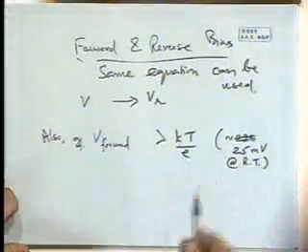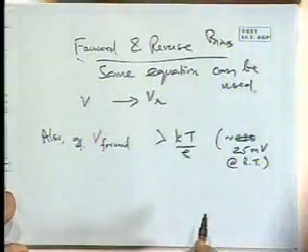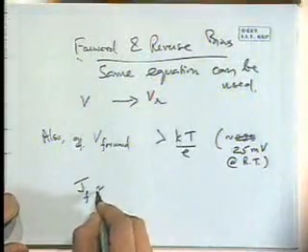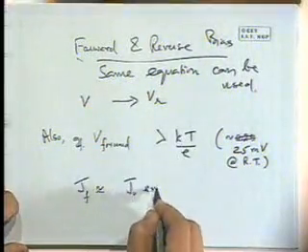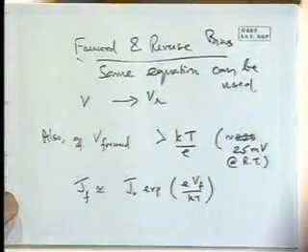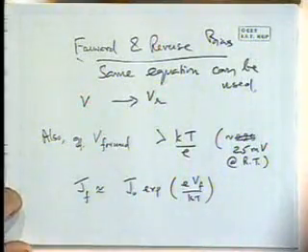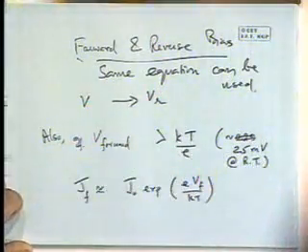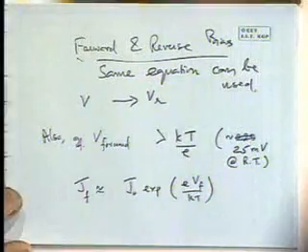So if the forward bias is more than about 25 millivolts, then our equation J is approximately J0 exponential eVF by kT. In other words, that minus 1 term there can be dropped if you're talking of forward biases larger than about 25 millivolts.